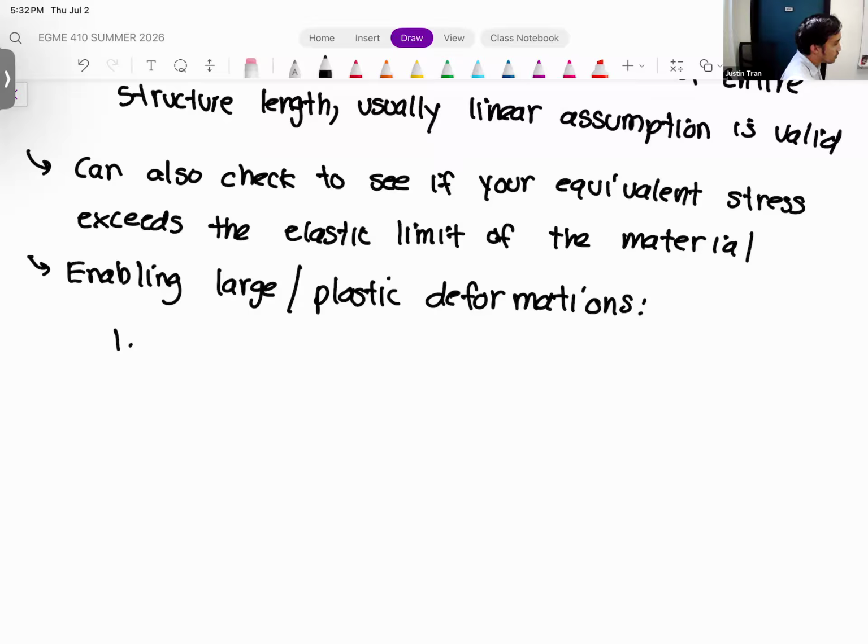If you go to the settings within the simulation itself, which I say as someone that's done this, but I know you guys have never seen it, there's a section within ANSYS Mechanical where you can change global settings. There's a way to enable large/nonlinear deformations.